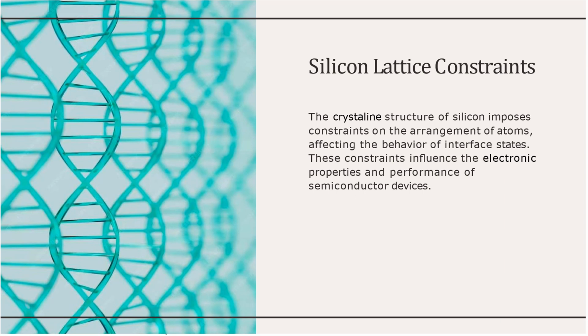The formation of dislocations, which are line defects that occur when the lattice is distorted by external stress and thermal mismatch. Dislocations can act as sources or sinks of carriers, depending on their type and orientation. Dislocations can also interact with other defects or impurities, creating complex defect structures.